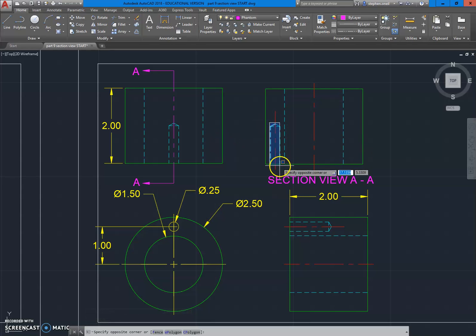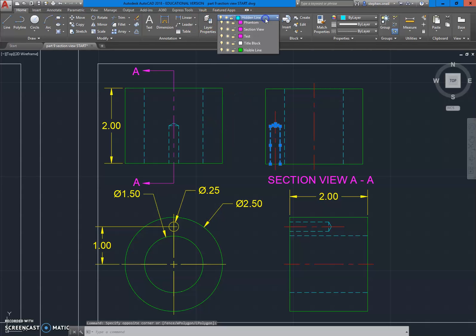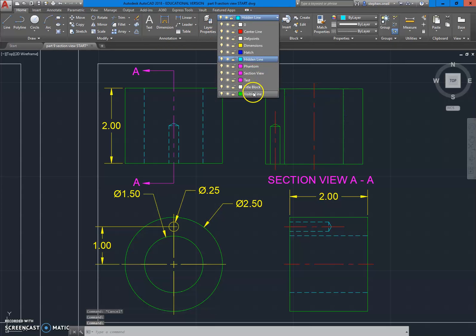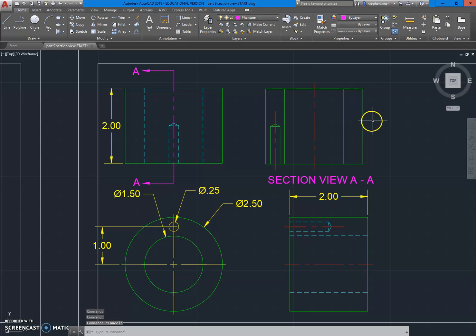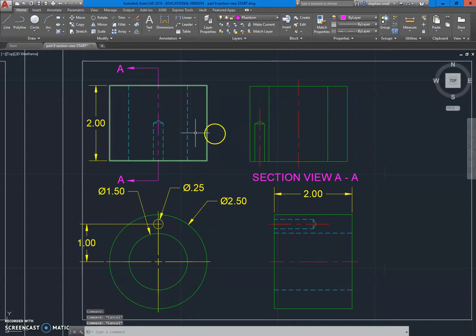The only difference is take the lines that make up the hidden hole, and now they are what? They are visible. So is the hole that you just cut through now visible? Is it not? Indeed. And since the hole is cut in half through the midsection of the part, you see nothing but blank space inside each hole. But what you see in the cut faces here and here are hatched.